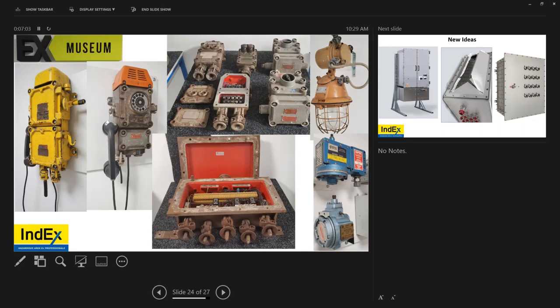We can drill into explosion proof enclosures, but not flameproof. Correct. But it's not the greatest way of doing things. It causes these confusions. How to calculate free volume? That's for the testing laboratory to do.